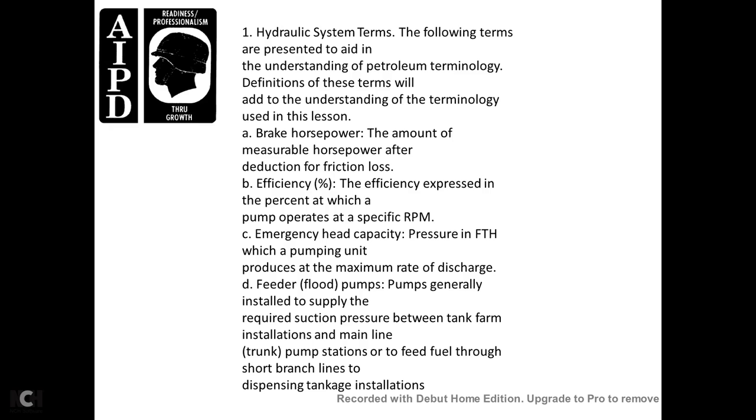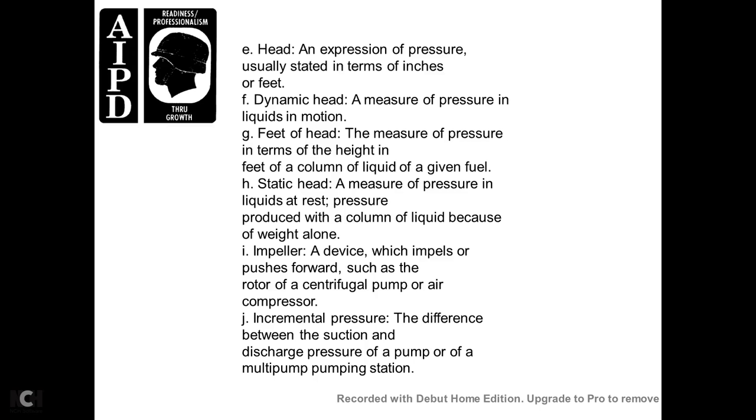Feeder: flooded pumps generally installed to supply the required suction pressure, as in a tank farm installation, mainline trunk pump station, and to feed fuel through short branch lines to dispensing tank installations. Head: an expression of pressure, usually stated in terms of inches or feet. Dynamic head: a measure of the pressure of liquid in motion, in feet of head. It is a measure of pressure in terms of the height in feet of a column of liquid, in this case fuel.